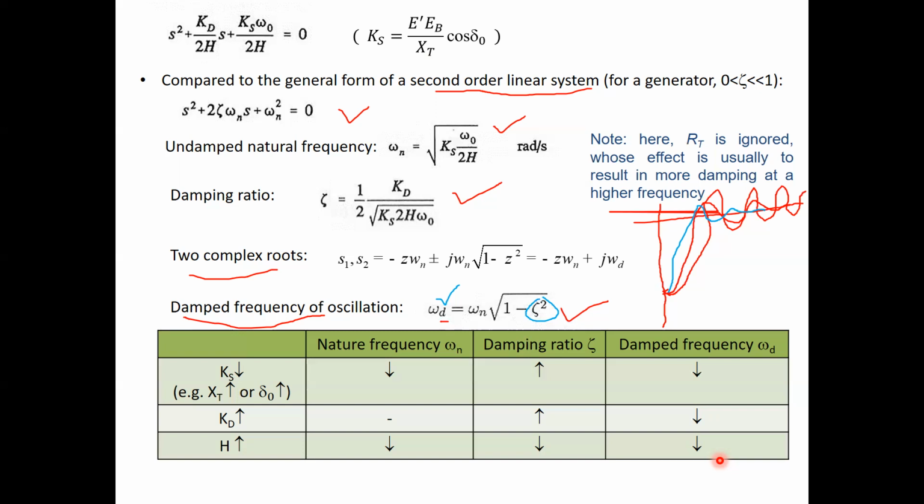We are not discussing that part here, how your excitation system is going to affect the damping ratio and the frequency. We are only discussing the system, that means the generator basically, and the load, because this you get from the generator, this from your load, and this again from your generator here. So how do the system parameters influence the rotor angle behavior characteristic? This is what we are discussing in this slide here, right?